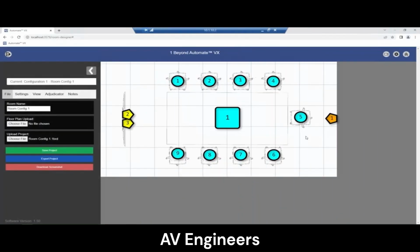It is crucial that the measurements in your room design are accurate in order to ensure that Automate VX functions properly. If any of the measurements in your room design are inaccurate, it can lead to errors or mistakes in the software. Start by checking all of the cameras in your room to ensure that they are perfectly level both on the tilt and roll axis.